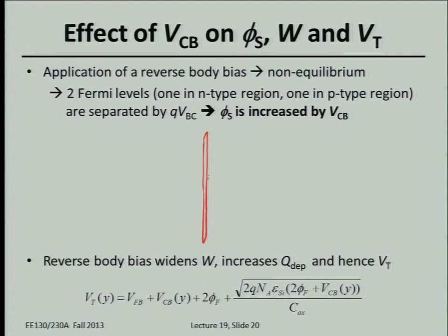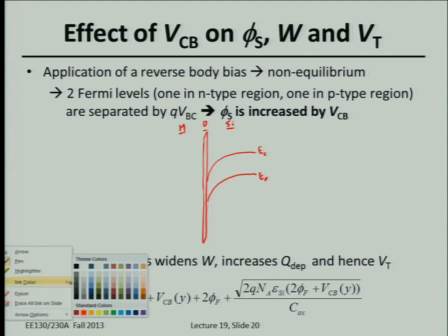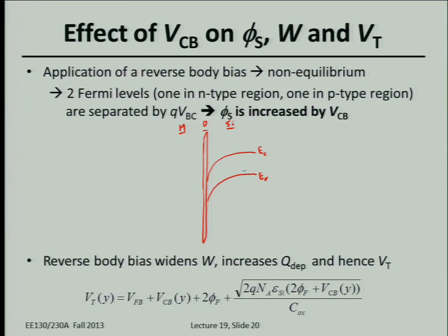We've formed an inversion layer. I'm going to exaggerate here. So here's the oxide, semiconductor, metal. The bulk is P-type silicon, and the surface is N-type. So EF is near EC at the surface, since this is inverted. I guess I didn't exaggerate this enough, but you see, there can actually be a difference here between the Fermi level in the bulk and the Fermi level at the surface.